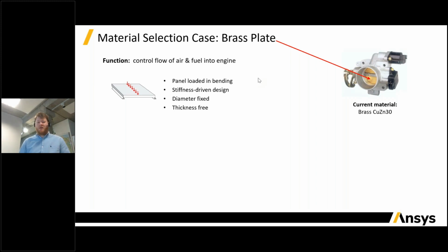Well, imagine you had a material that was a lot weaker. Let's say it had a yield strength that was half of what you're currently using, but it was 10 times cheaper. So you could make a component that was a little bit thicker, and you would still have good mechanical properties, but you'd be able to save a lot of money potentially.